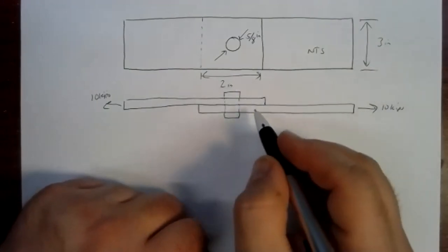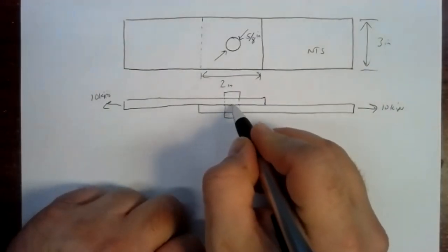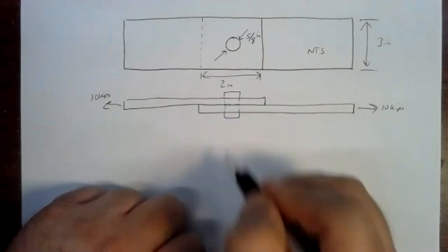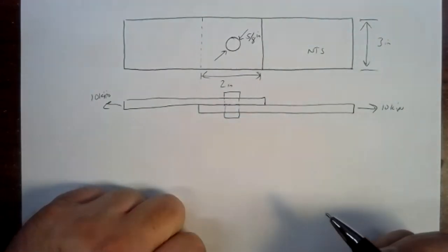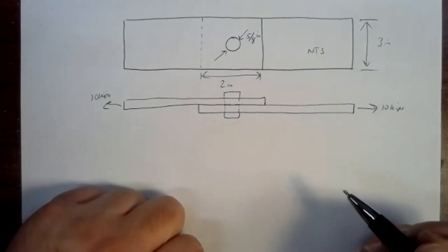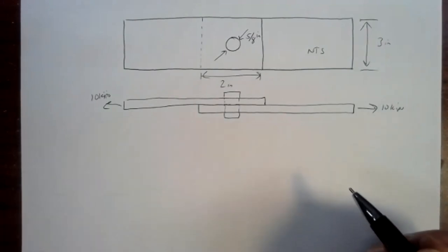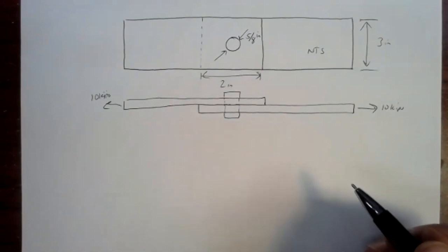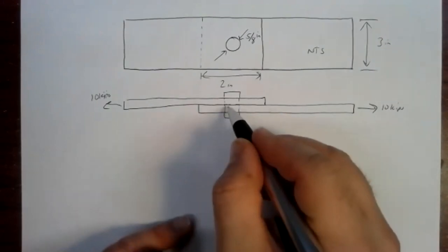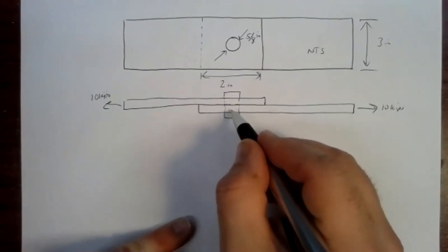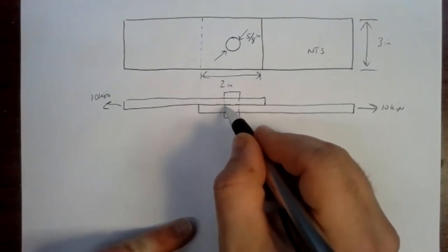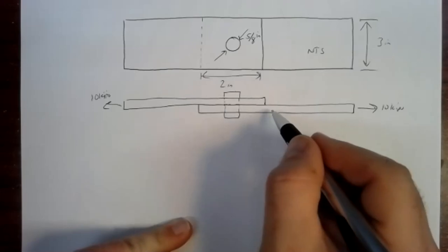Now all that 10 kips of force is trying to shear through, trying to cut through that diameter of that pin. For those of you who've been through sheet metal, think about what you were doing with the rivet shears when you had to cut a rivet down to size so you could install it. Basically doing essentially this. You had one plate holding the rivet, another plate that would push by it and cut through.